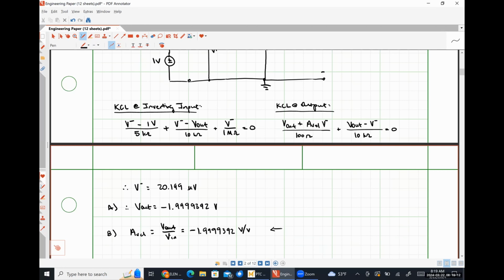Okay. Now, I haven't explained this yet. I don't remember, but I don't think I touched on it. The open loop voltage gain of an op amp circuit isn't necessarily a fixed quantity. Let me explain explicitly what I mean. If I were to get a package of, let's say, 10 op amps made during the exact same fabrication run, the average value of those would be what's on the data sheet, but the open loop voltage gain of each individual op amp is going to vary some amount.